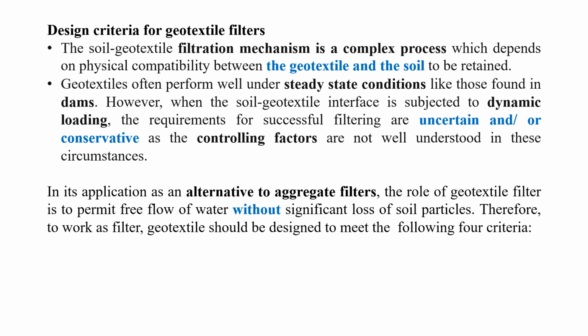Therefore, to work as a filter, geotextiles should be designed to meet the following four criteria. So whenever we design the geotextile to work as a filter, four criteria should be met. What are the four criteria? First is retention capability, the ability to retain soil. The geotextile should have the ability to retain soil.